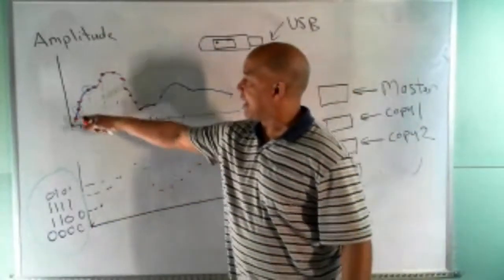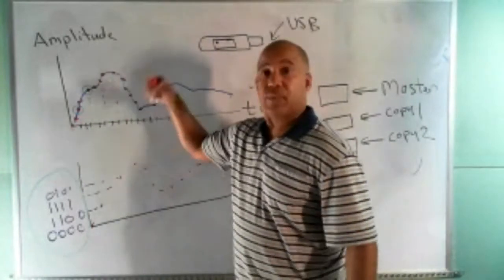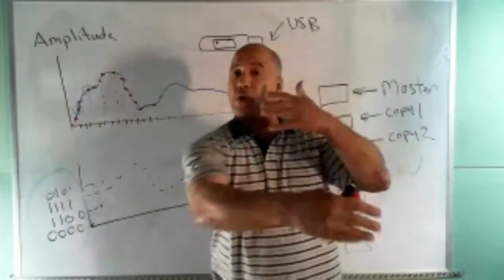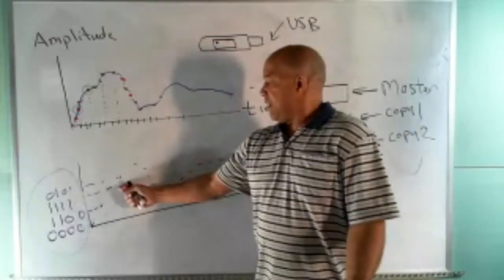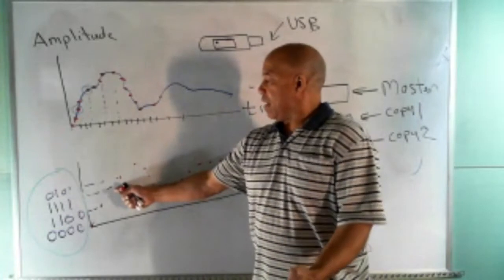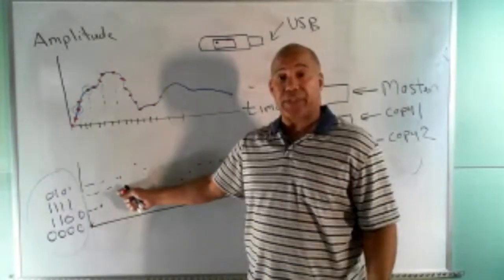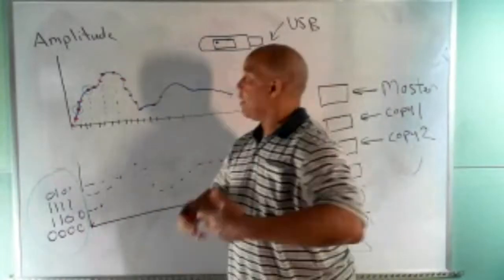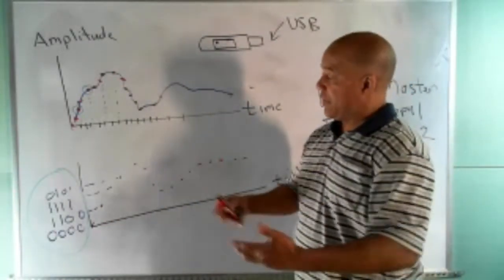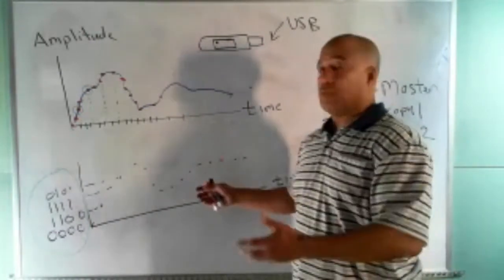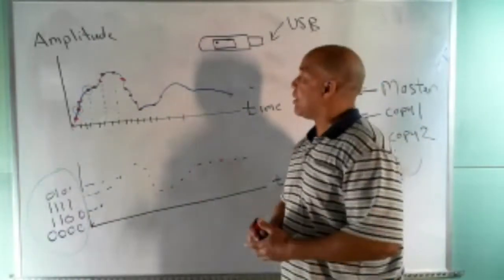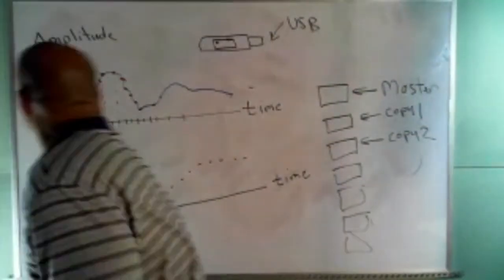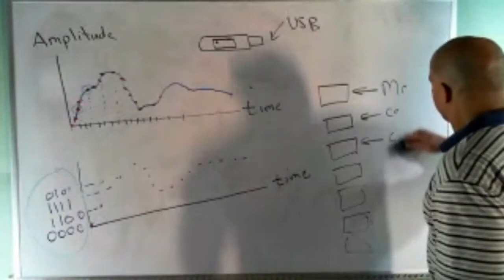Well, we took the analog signal, and we sampled it. And then each one of those samples, we represented with zeros and ones, and we can store those zeros and ones. Each code represents information. If I need more information, I increase the resolution. I got more codes. I got to have more digits to represent it. It's going to take longer to move around, and there's disadvantages to that. It's a trade-off. Now, let's talk about binary a little bit more, and then I'll let you guys go.